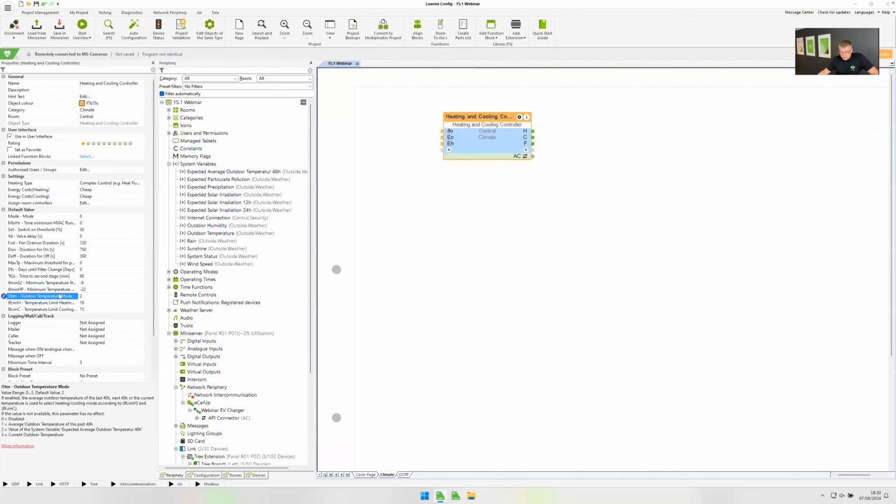And last but not least, you also have the option for current outdoor temperature. So whatever the outdoor temperature is now, this is what the system's going to respond to. And that's what we found works most effectively for our building, our UK headquarters, because the insulation isn't amazing. So what the outdoor temperature is heavily influences the current indoor temperature. But if it was a better insulated or newer building, it's going to operate a little bit differently. So that's why these options are now made available.